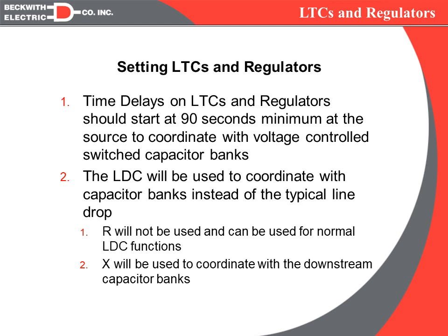But again, it makes it a little harder to coordinate because we're trying to get our band centers on our regulators and our capacitor banks to be the same, so that when the voltage is at a certain level, the cap banks and regs are timing, but the caps will beat it. So if we apply an R, we're biasing the voltage at the source and therefore biasing the band center. So our recommendation is in this type of architecture not to use the R at all.